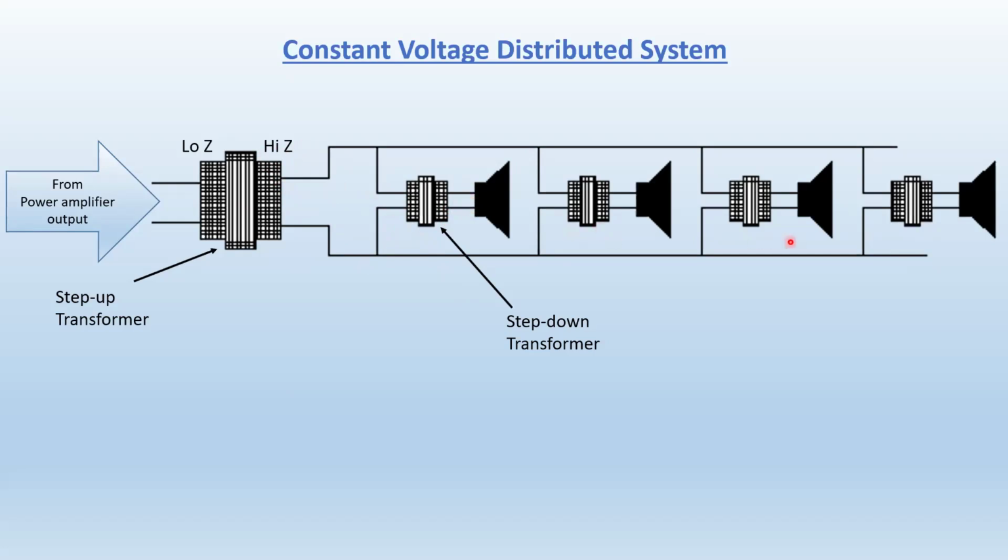And if you do that, you do not have to have the series parallel combination. You can just keep adding speakers. So you're going to pull a long, long line along the whole hallway. You're going to interrupt the wire, put in a speaker, interrupt the wire, put in a speaker station, and so on.